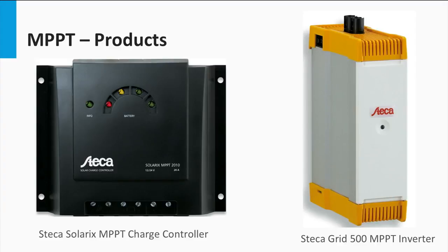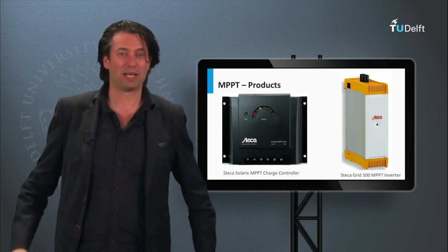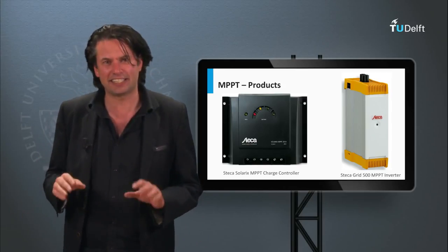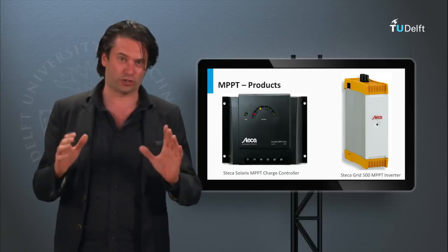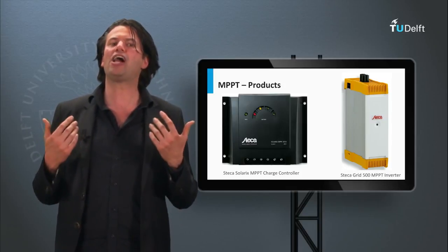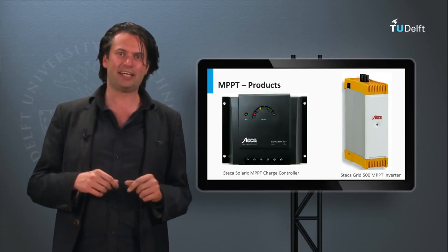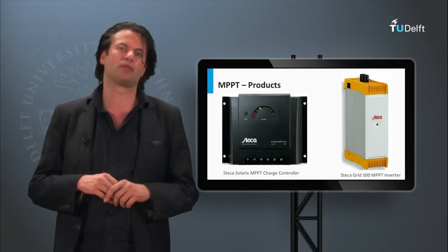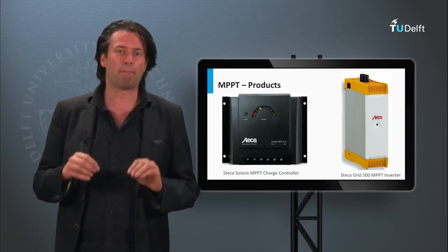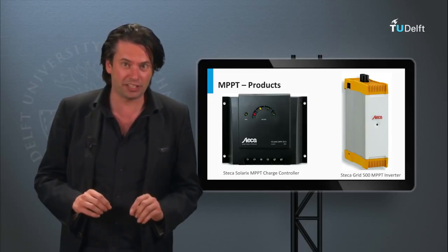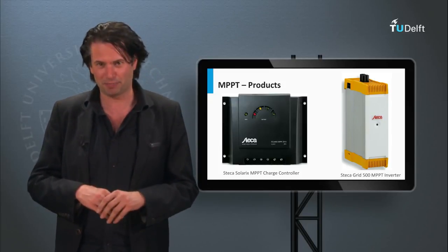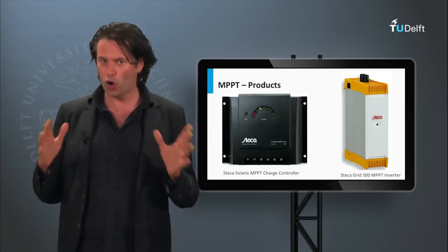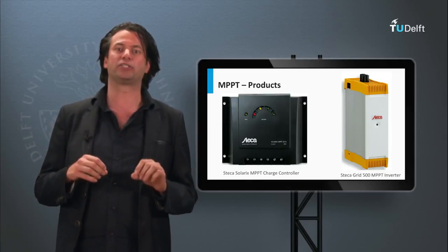In modern PV systems, the function of the maximum power point tracking is often implemented within other system components like solar inverters and charge controllers like shown here. Please note that the list of techniques and typical implementation are definitely not exhaustive. In fact, several algorithms and implementation techniques exist in practice as well as in literature. There are scores of scientific papers, patents, and proprietary technologies existing in this rapidly growing space. In view of time, we have covered only the most common maximum power point tracking techniques.